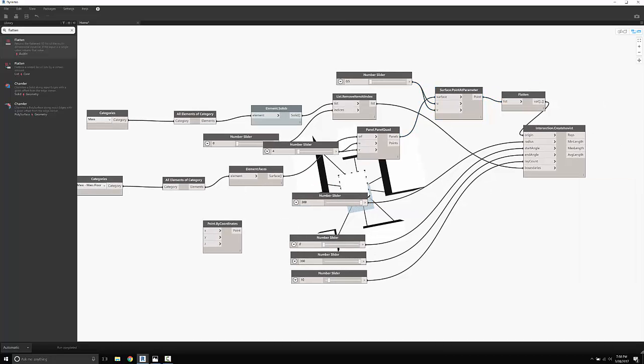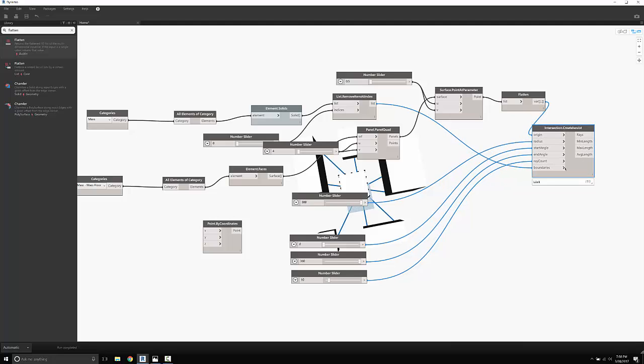Okay, it didn't crash because it's inferring that the shortest list of objects is the most important, and so right now the boundaries are set to the shortest list of objects that are in there. So I'm going to right-click on this and change the lacing over to longest, and now the computer should think quite a bit.